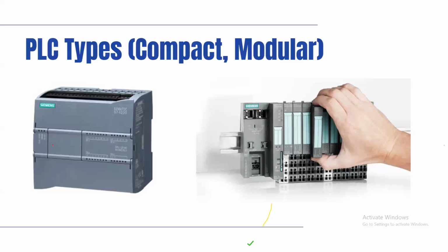Okay, so I would say it depends on the feasibility in terms of expansion in the nearest future. If the project is just for that purpose in the next 10-15 years, I would use a compact. But if there are chances of expansion in the nearest future, I might need to use a modular PLC.